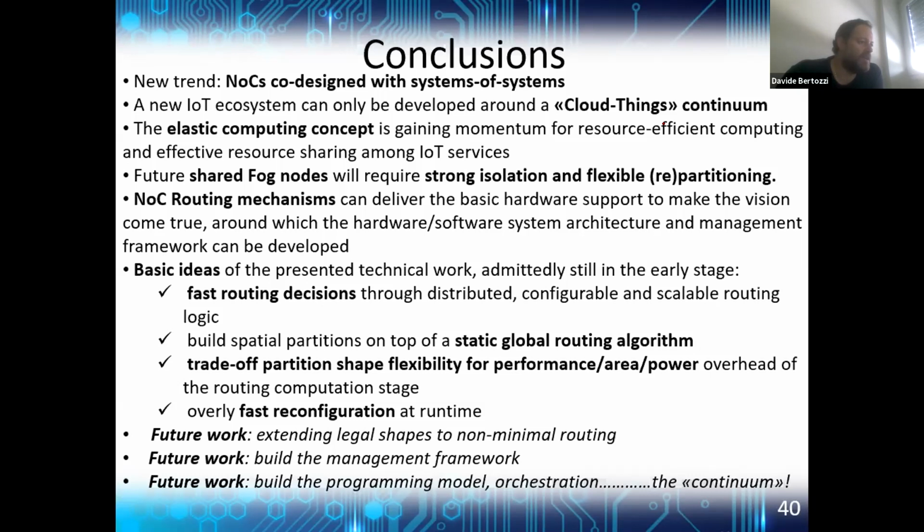Another very interesting question that would require tighter interaction about the specific use case this question is referring to. I mean, the general question is, in the implementation of a NoC, can nodes operate at different frequencies like DVFS? If so, is it possible that this different frequency domain could cause bottleneck on packet routing? The answer is absolutely yes, absolutely yes.